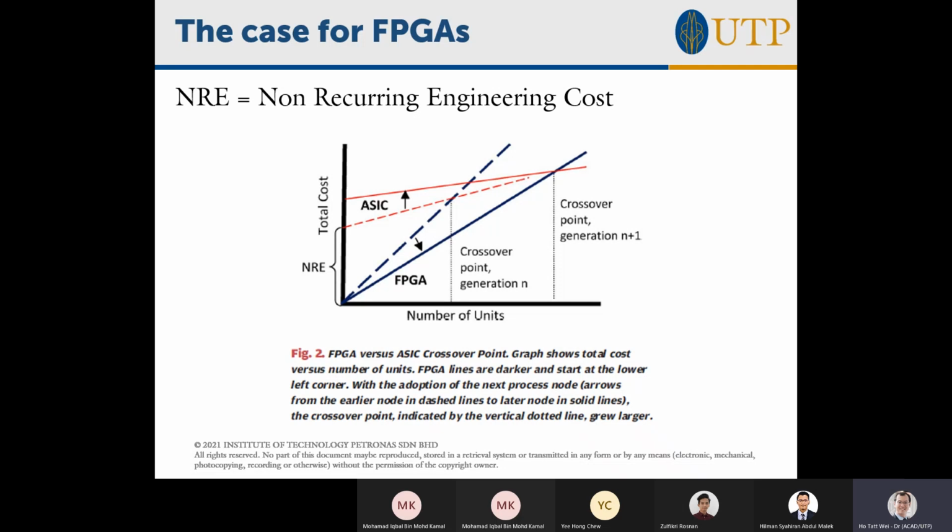And again, here I want to compare and contrast. If you talk about programmability, most of you will just think embedded controllers. I just buy a microprocessor and all that. That's one way you can do it. But the interest in FPGA is because FPGA is a special purpose logic. They tend to be faster because you don't have the fetch, decode, ALU, and store cycle, right? If you want to implement a logic, it's just that already. It's just one clock cycle, you get the logic.